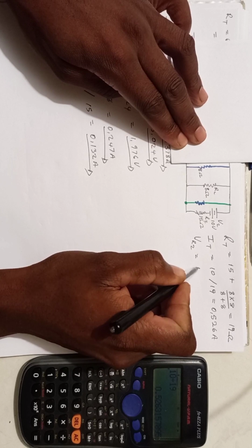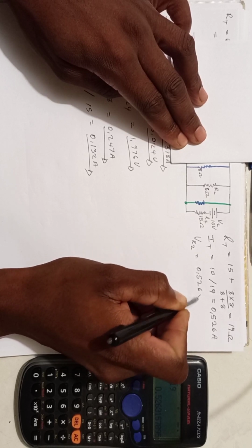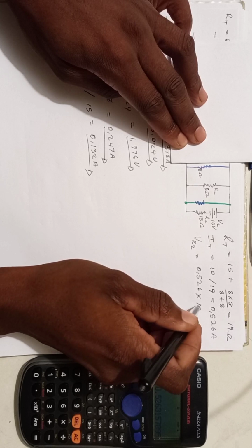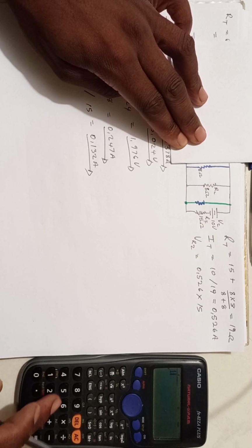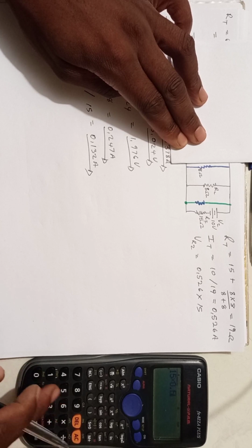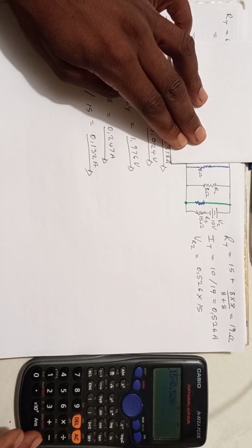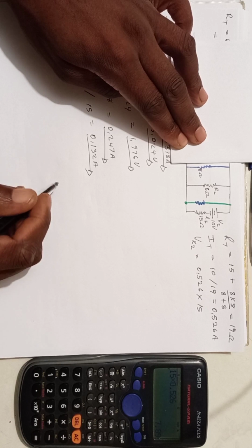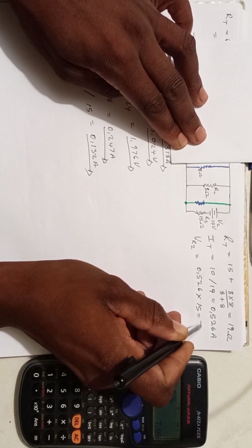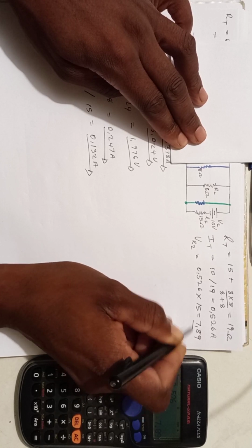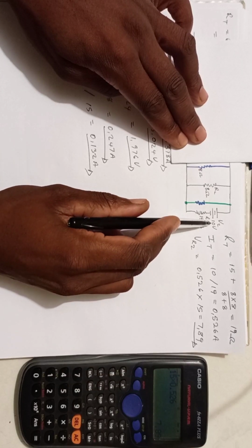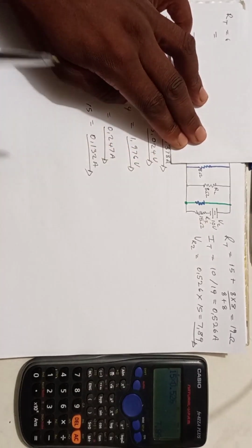This helps us to calculate the volt drop across R2, which will be the product of current and the resistance, times 15. So let's just say 15 times 0.526. Something happened that I don't trust, which is why I'm punching this in again. This is going to be 7.889.